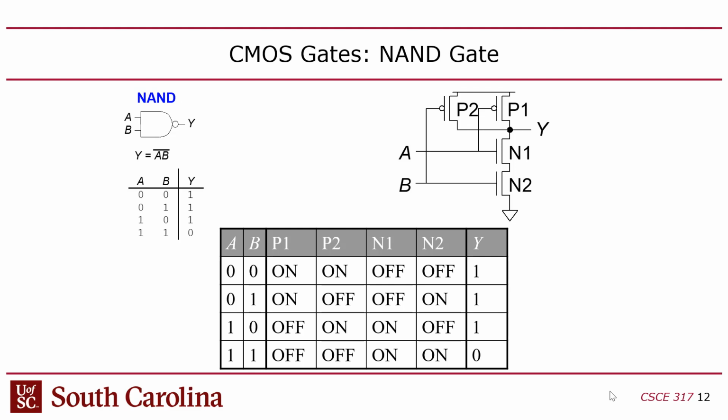As long as one input is 1, you're going to get a true output. So that doesn't work either, right? There's no way to pull down, because there are no rows in the truth table of an OR gate where you have a 0 output with at least one input to pull down. Does that make sense?